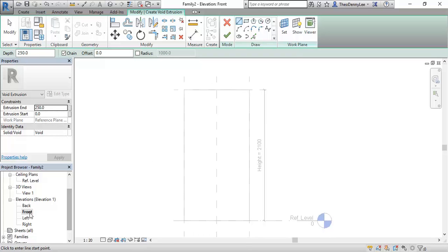And so just by going to the front view, it's picked up the reference plane. It would actually be called front, you can see there. Really, we should be doing this whenever we create anything that's repeated. Any casework. Not just copying it across room by room. Anything that's repeated. Any piece of furniture particularly. This will be handy.